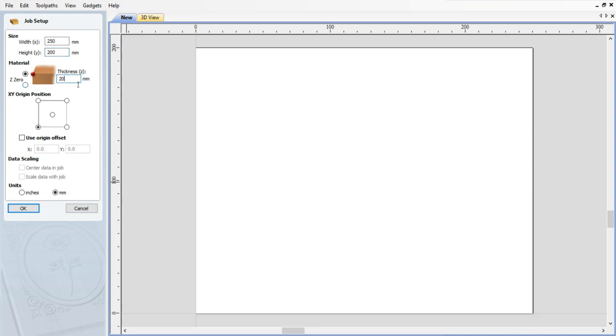And then the material thickness, binigay ko rin to. This should be set at 15 millimeters. So set natin as 15 mm thickness. Make sure the zero reference for the z-axis is at the top kasi pwedeng bottom, pwedeng top, no? The reason for this, very important, is that dapat pareho tayo ng understanding ng machine. The machine sets the zero reference of the material or the wood in this case to be the top portion of the material. So ito yung z equals 0 natin.